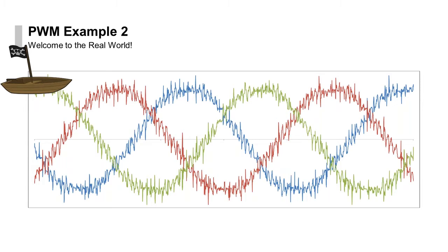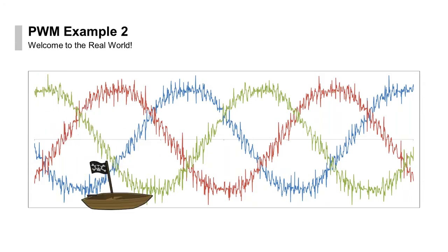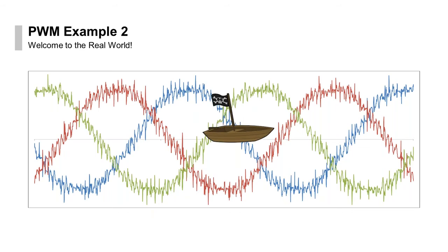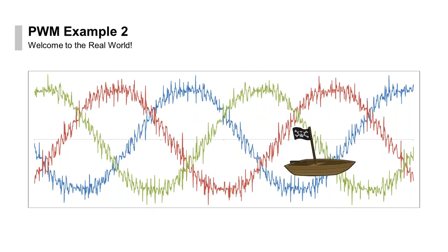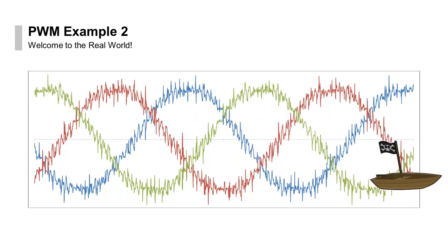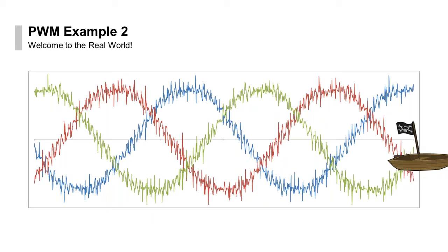So what we're going to do here is put our boat back on, and now we get to talk about what your equipment is experiencing as it's riding these waves. This is not a comfortable situation for most equipment. This is why we have inverter duty motors. This is why properly designed VFD systems actually have special cabling, insulation, and things of that nature. This high frequency is tough on equipment.